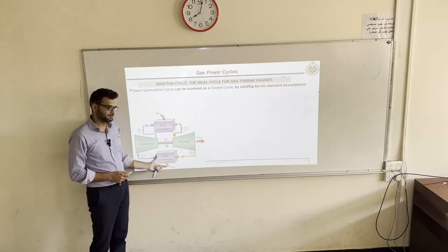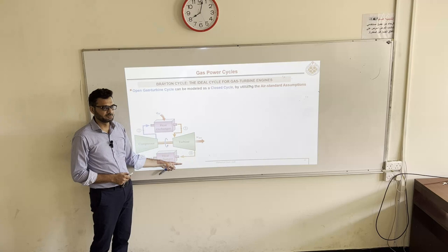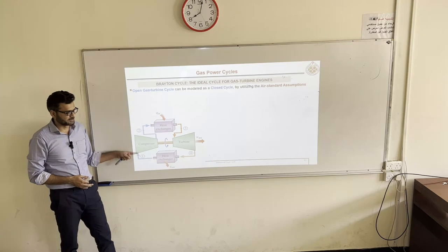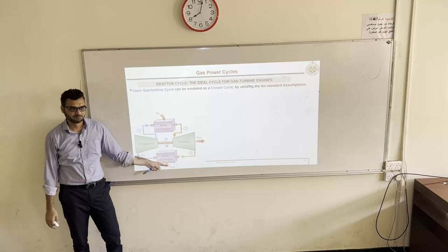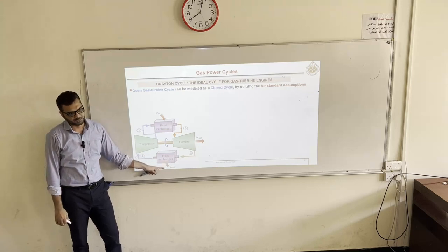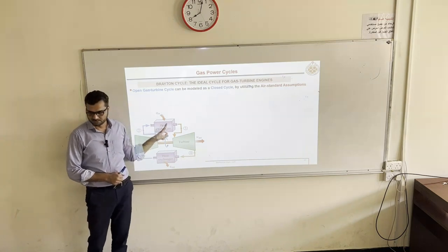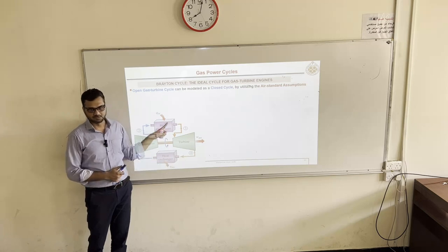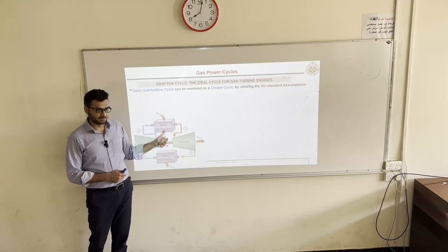Same here. It's not like Otto cycle or diesel cycle. Here the fluid goes into the ambient, to the ambient pressure, and at the same pressure it is entering. So what is happening in the ambient, only heat is released to this constant pressure ambient. So this process is also constant pressure heat rejection, constant pressure heat addition. In Otto, both were constant volume. In diesel, it was constant pressure and constant volume. In Carnot, isothermal.